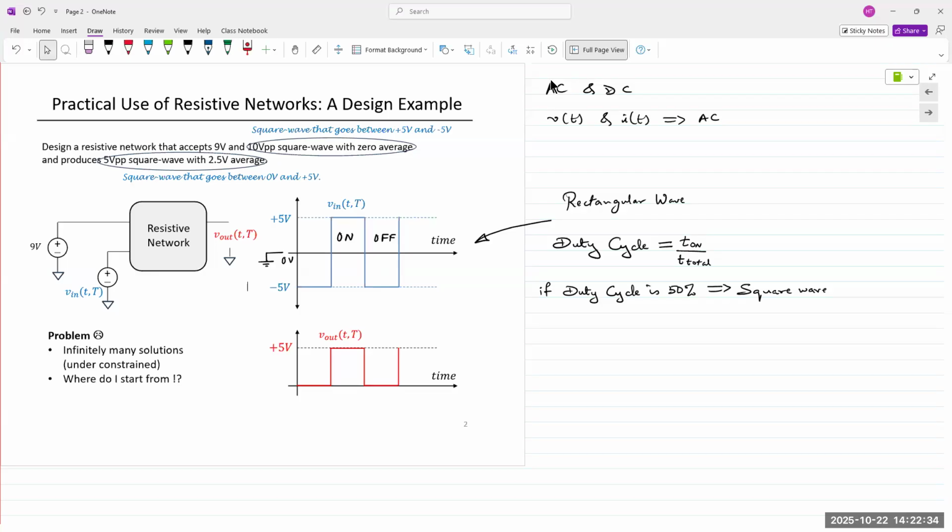For a pure waveform like this one, half of the waveform is above 0 and the other half is below 0. So this waveform goes plus 5 volts and minus 5 volts. So it has a positive peak and a negative peak. It's 5 volts above and 5 volts below, so the total swing in the amplitude of this waveform is 10 volts.